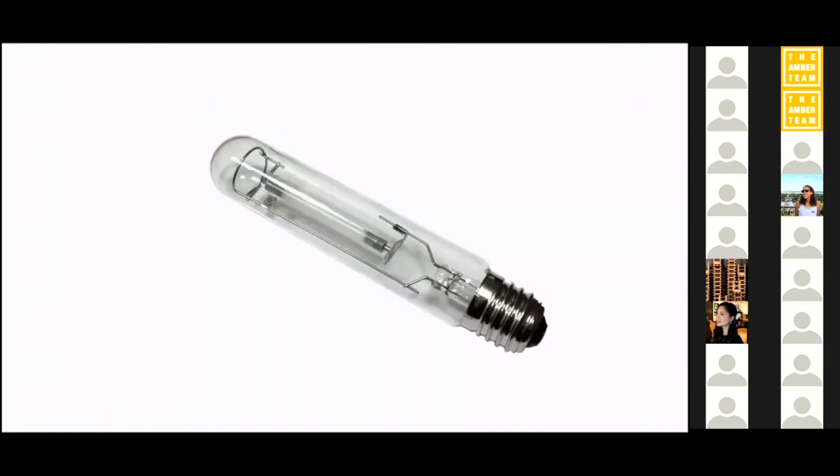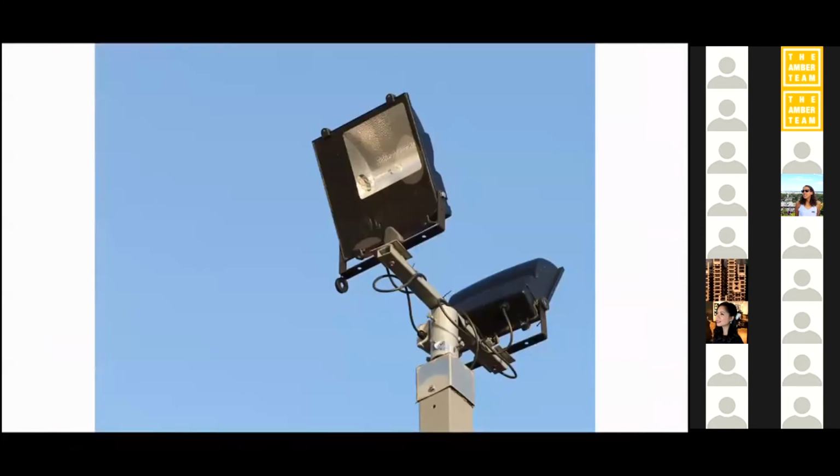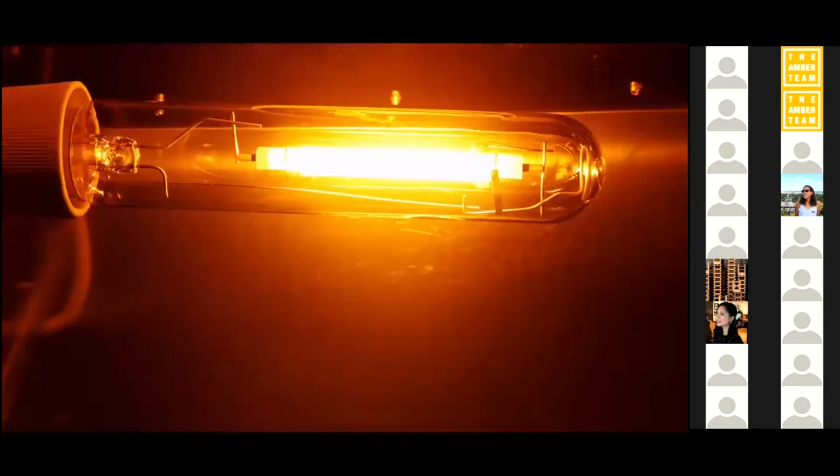And they look like this. In some ways they're like fluorescents, and actually fluorescents are called discharge lamps. These are high intensity discharge lamps, and there's a gas, and some of them look like they can screw in a traditional Edison screw, but they can't. I mean, you can screw it in, but nothing will happen. It doesn't light up. You need to have the ballast that regulates the current to make sure the thing starts and ignites and then keeps going. And you see them high in the air often.